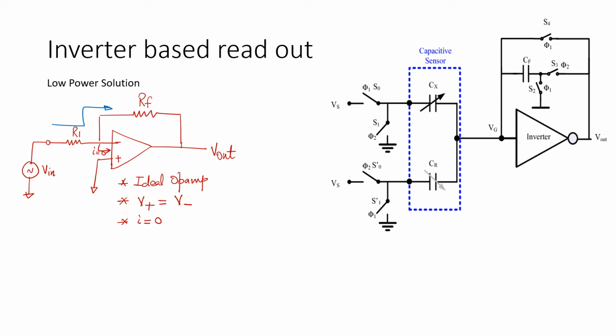Third condition that we will see is, with these two conditions we will develop, the gain is infinite, or to say infinite open loop gain. So the output V out is given as minus RF by R1 times VA. So this is the output.